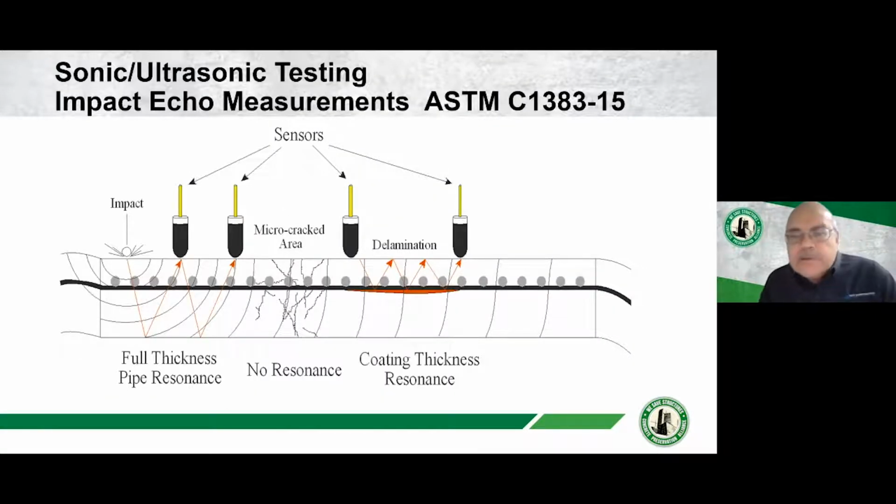Now, the first rendition was the pulse velocity information. There's a second ASTM procedure that documents how to record impact echo or pulse impact echo measurements. And we record the velocity and the impact echo measurements simultaneously. This is the energy that gets trapped within the deck and oscillates between the boundary conditions, the red line going up and down, up and down.